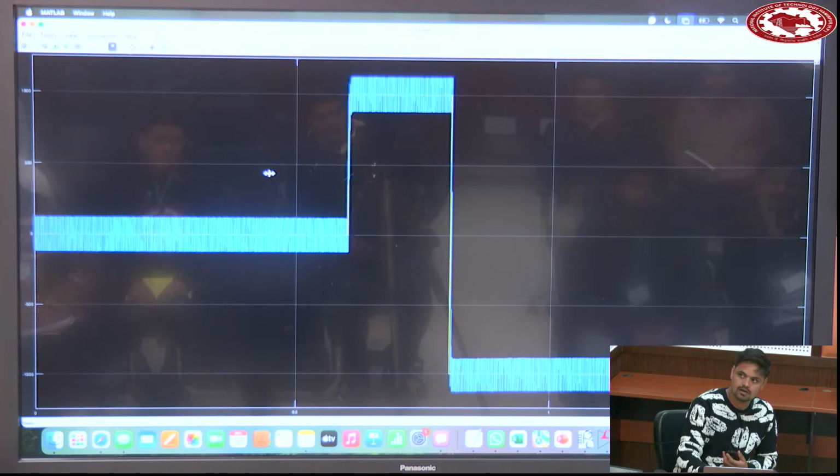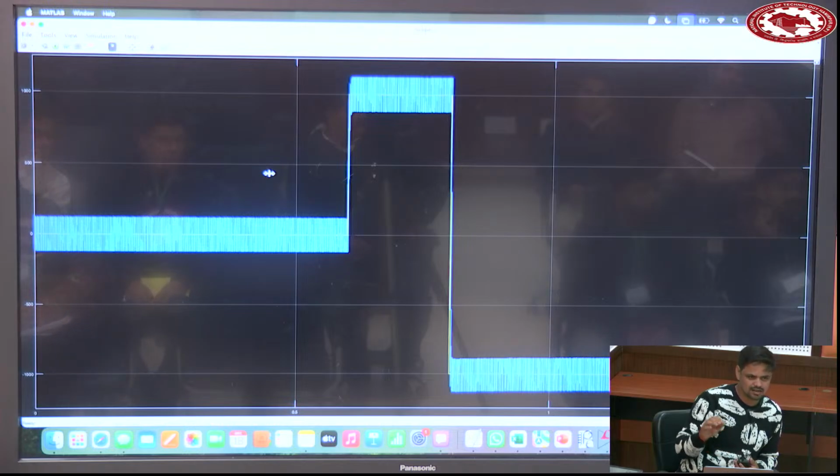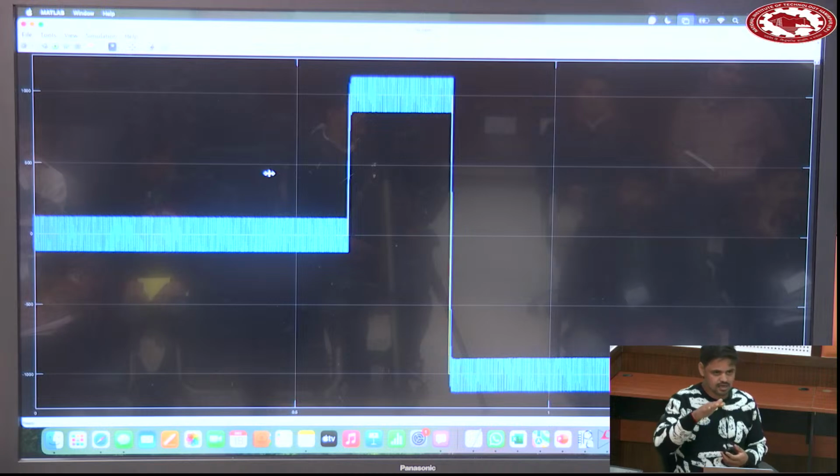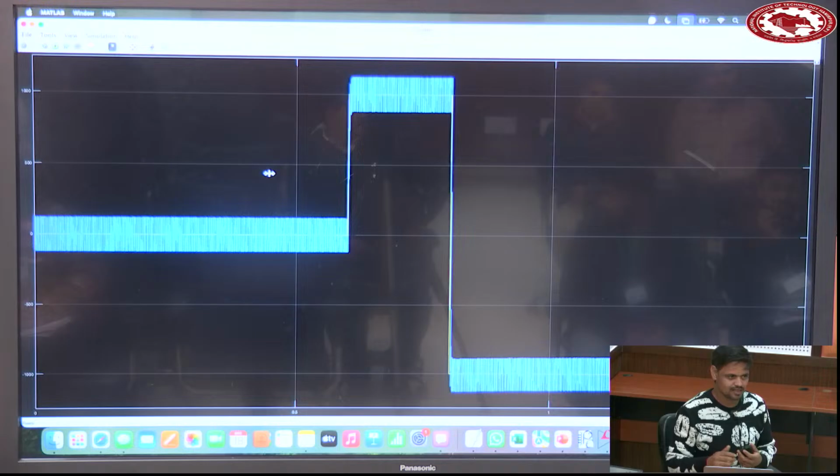This is the switched model. Correct? Ripple is approximately 10% of the rated current. It depends on the inductor you choose. You can choose for 2%, 1%, but industry applications are okay with 10%, 15% ripple in the current. Because if current ripples are going down, you will need a higher value of inductance. Higher value inductance means a big size of inductor, and cost will increase. So there is a compromise between size of inductor and